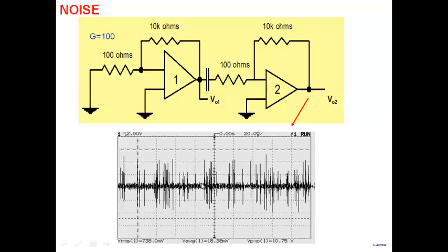Now, when something is random like this, you don't specify a random voltage only in terms of the peak value. A better measure is the RMS value, root mean square value. If you can read here, the RMS of the output is 738 millivolts. So let's take it as a round number: 750 millivolts is the RMS voltage here. A random signal that you see.